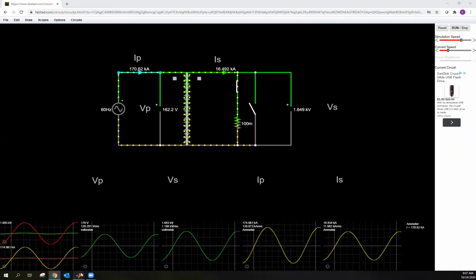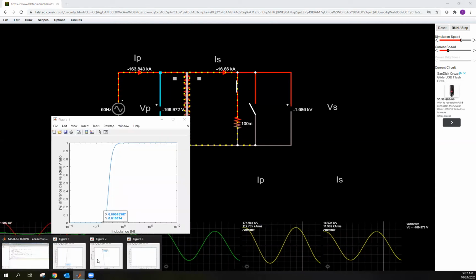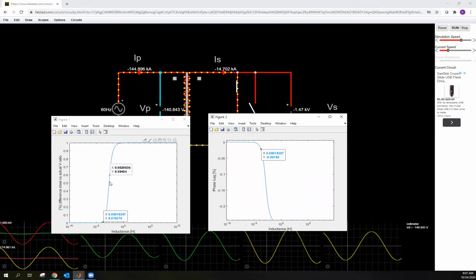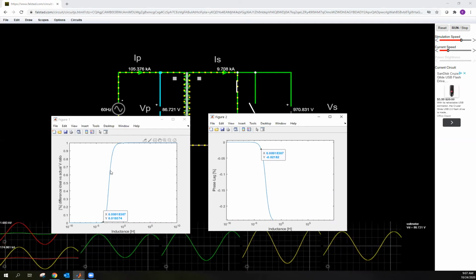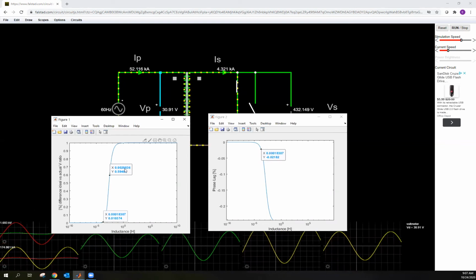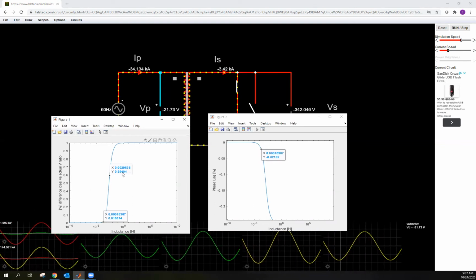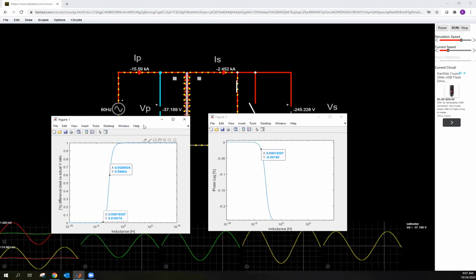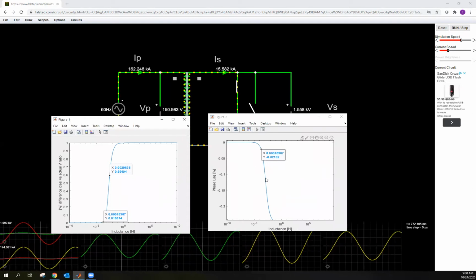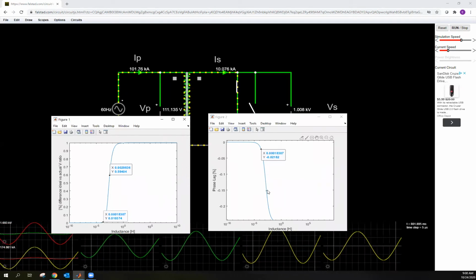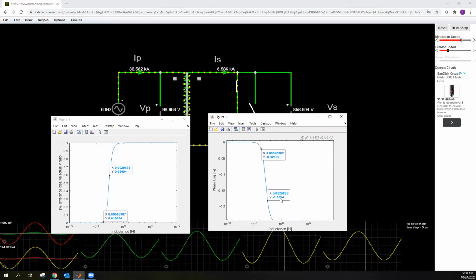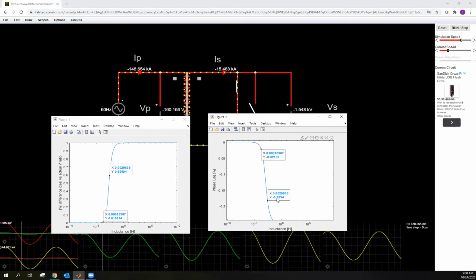Now, let's say we had this same horrible transformer situation and I didn't pick the inductance well. So let's say I picked right there. And what is this saying? If I even went up to 0.0029, I would expect an error of 60%, right? So instead of a 10-to-1, it would be a 6-to-1 kind of thing. Over here, if I get the same number, I would get a phase lag, here it is, of 18%. So I'd be phase shifted by 18%.